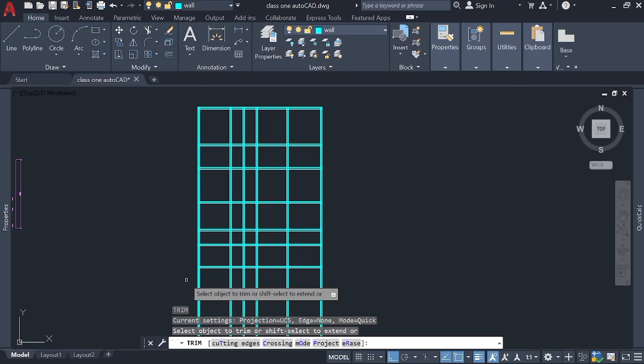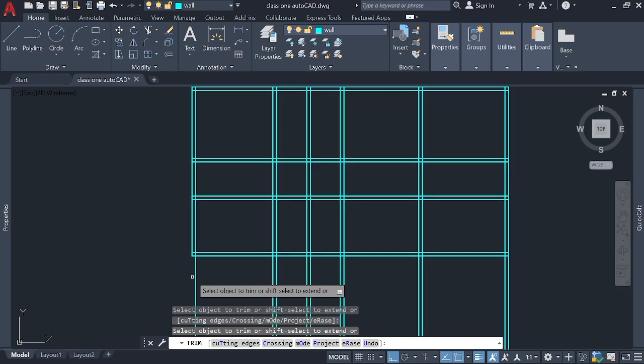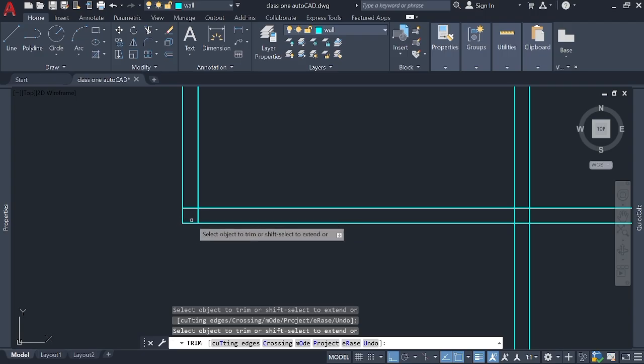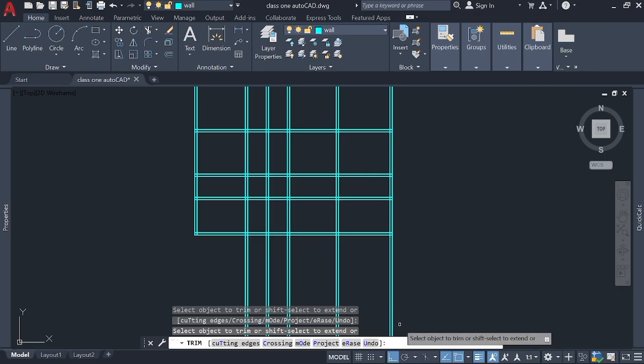So once you press enter once, now if you move on any line, it's going to disappear. Click on it, it's going to disappear. You see, I click on it now. Left click. I've trimmed that part out. Click on this one now. You have trimmed it out. You see, this thing now is trimmed just from here to this perpendicular distance. But had this line not been there, it would clean trim to the next perpendicular distance. It will always stop at the next perpendicular distance. But if it was running straight from the beginning to the ending, trim everything completely.